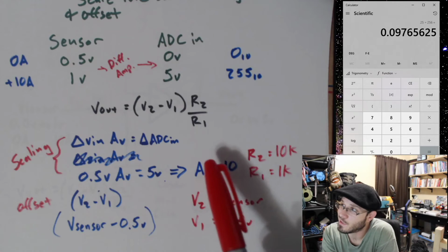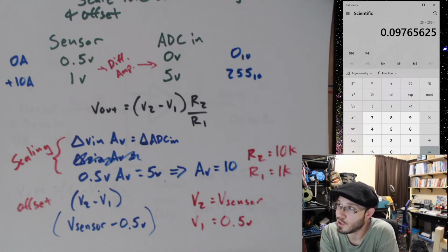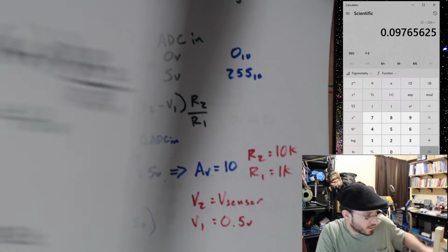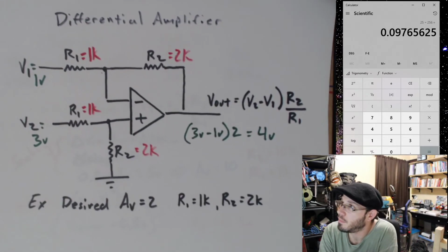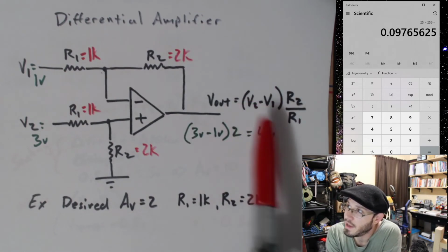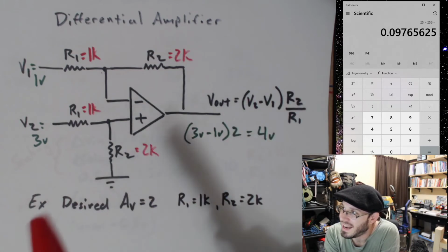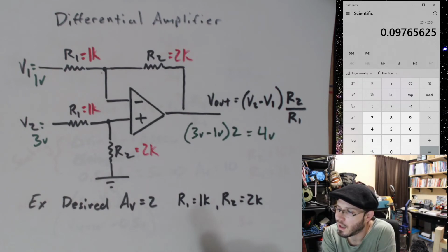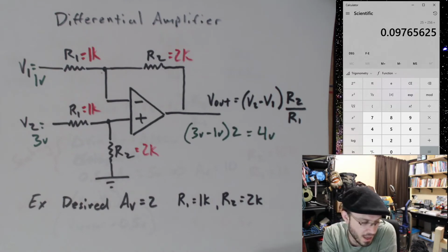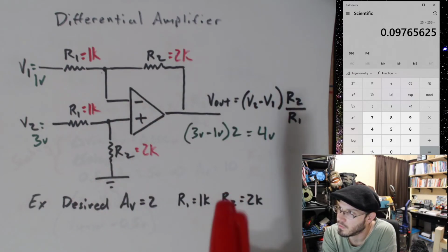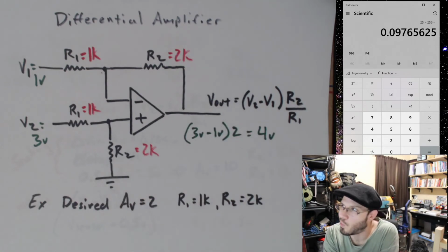Now, I think it's actually super quick to do. If you have a page of notes that just has your differential amplifier, and you look at this equation, you can figure out the values in order to fit any sensor to the usable range of your analog digital converter. Okay, so as far as preparing for the final, this one is going to be in there.